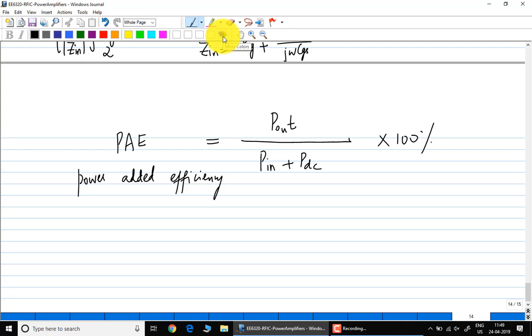Okay, now if you are not designing a CMOS PA, if you are designing some other PA, of course the CMOS transistor, you are lucky it has a high input impedance, but that's not necessarily true for other types of transistors. Okay, in which case Pin does really matter. Okay, if the input is not resistive, Pin really does matter. Okay, it's not just that. If you are building a CMOS PA, you are going to integrate it with the rest of the transmitter, right? So the output of the transmitter is also CMOS. It can drive this capacitive input, no problem, right?